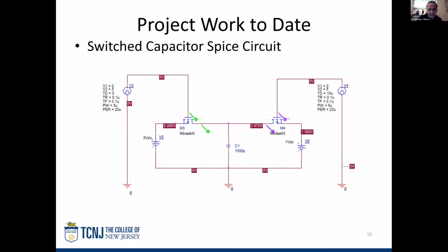So an enhancement to that topology is that, you may run into some accuracy issues when you actually build it, because you can never remove all the charge from that capacitor. That translates into a problem if you have a parasitic capacitor or a fringe capacitor across it that adds to it. So an enhancement to that topology is if you put the capacitor between those transistors, okay? And then you put another 2 transistors from those nodes to ground, and you control them.